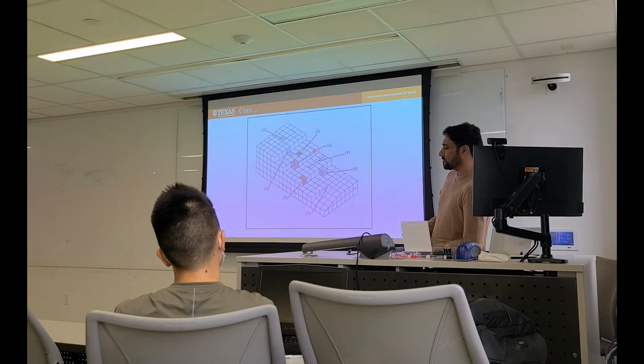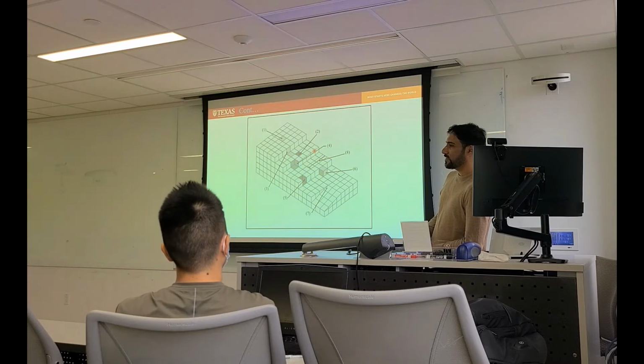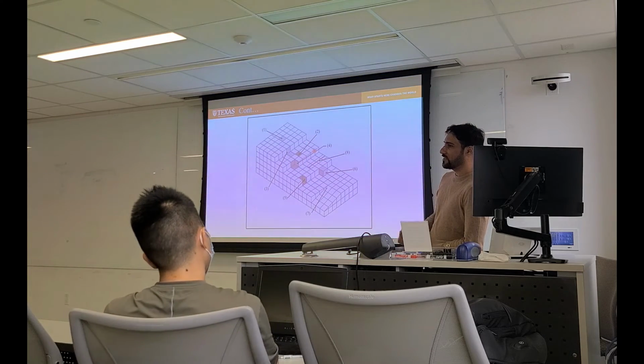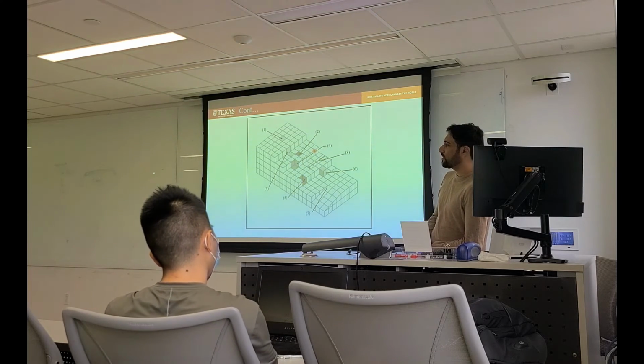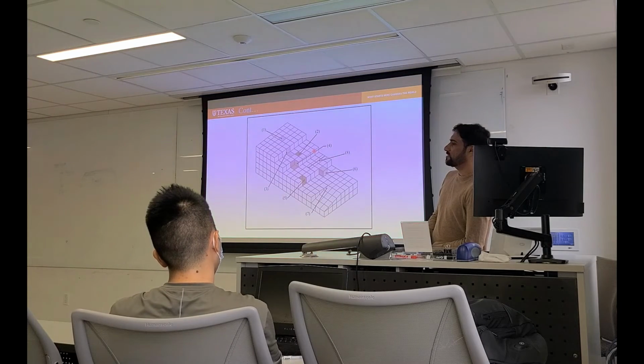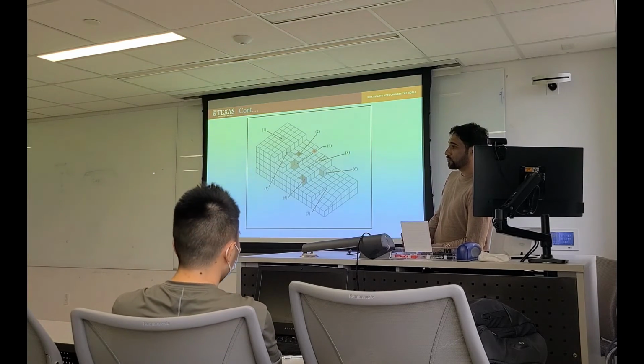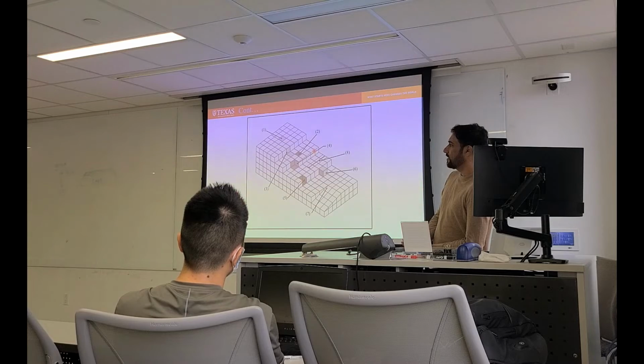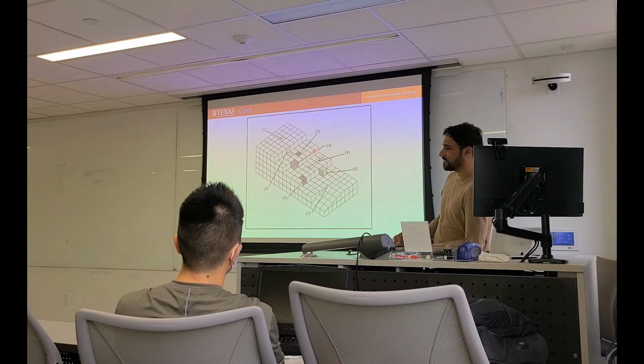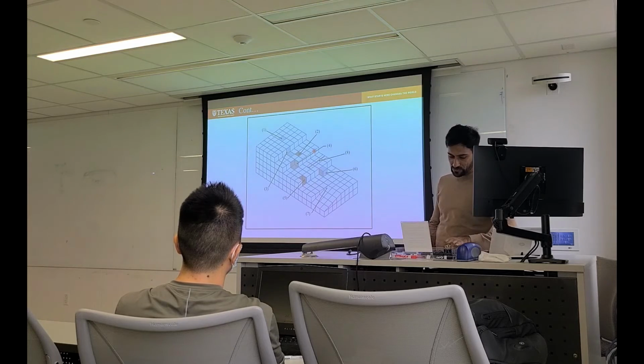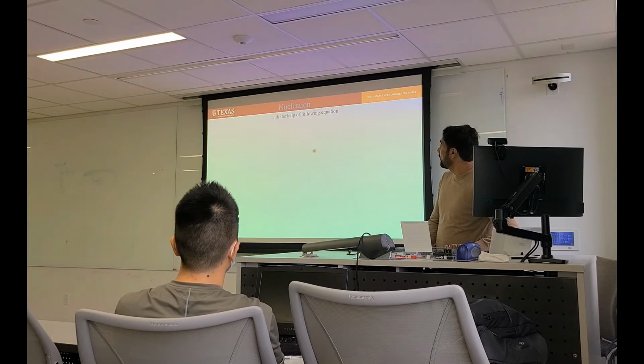So people clean the substrate before putting it inside the reactor. There is some chemical cleaning process. They can also clean the substrate at high temperature before growth starts. Then they can start the growth. The reason is to clean the surface and decrease the density of defects on the surface. So that is very fundamental.